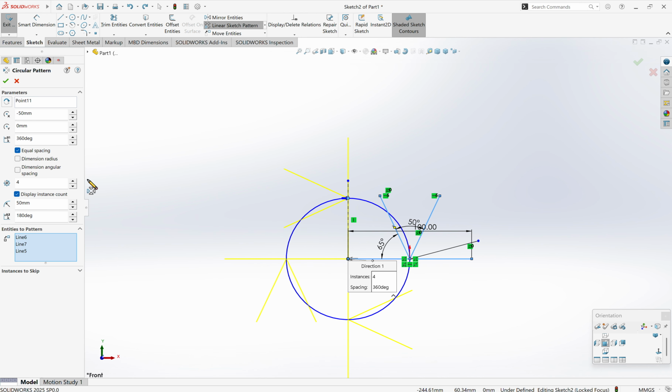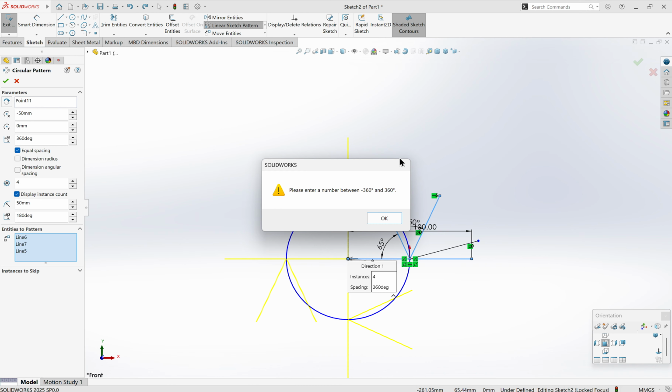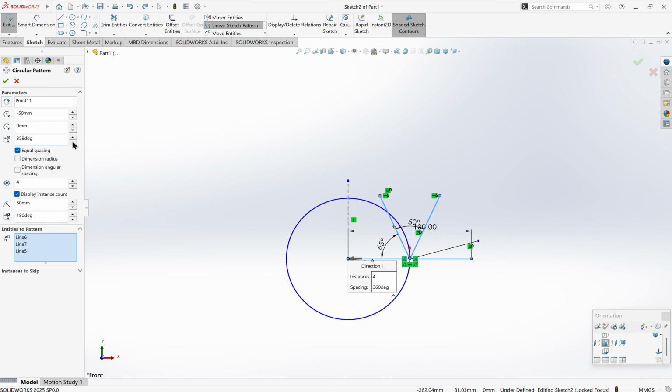Okay. Now, what do we need? It's the angle that you want to rotate about. If you change it, it's going to decrease the angle of it. Let's put it on 300. So you look, there's a change in it, 360, and it changes. And the amount of things that you want to copy, how much do you want to copy? Let's say it's like 9. And that's all for this. We don't need anything more.